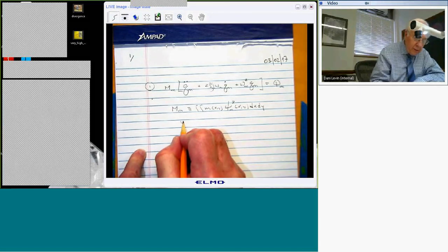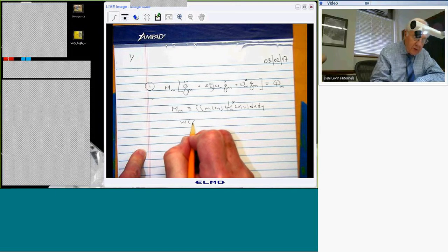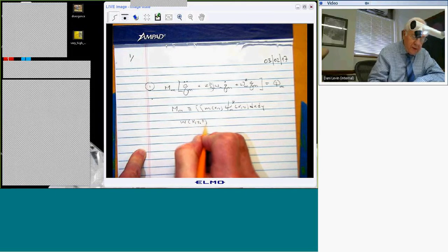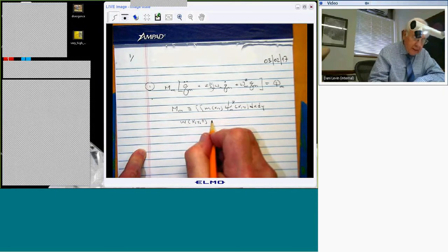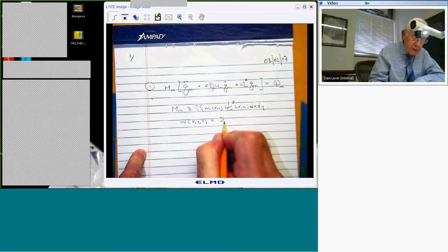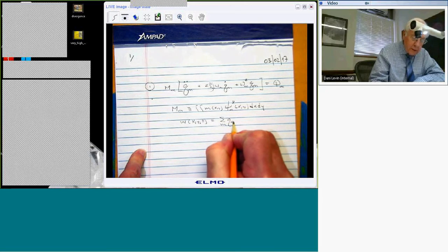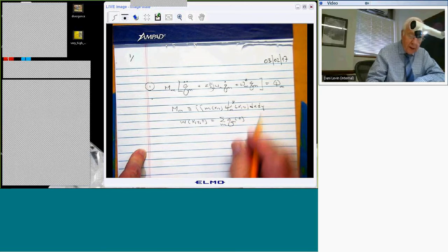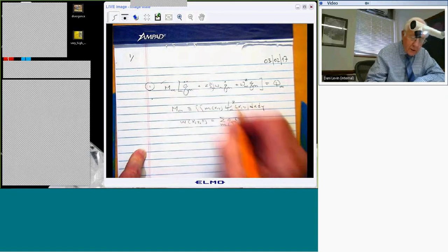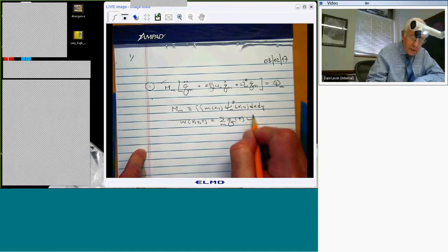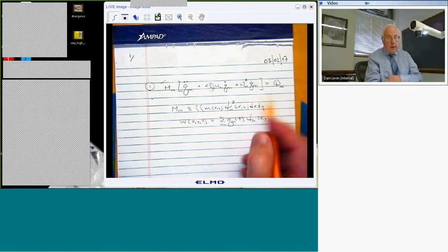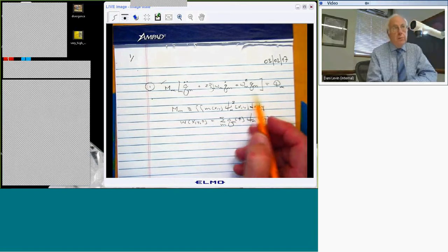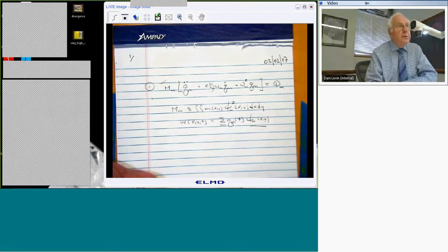And those functions are the functions in which we choose to express the deflection of this plate-like object in terms of a series, where the q_m are the functions of time, which we hope to determine by solving this equation, times these wonderful functions of x and y. And this compact form is dependent on choosing those functions to be the eigenmodes of the structure.